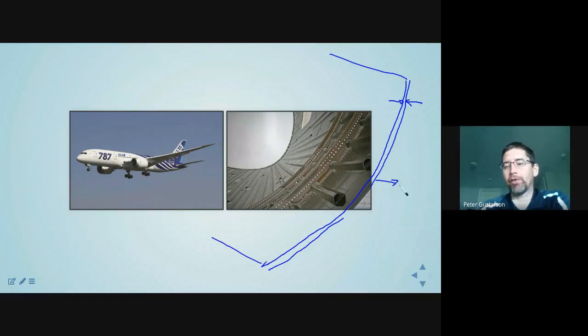Now, there's atmospheric pressure perhaps on the outside, and there's something perhaps slightly different than atmospheric pressure on the inside. These aircraft are often pressurized. So there might be an internal pressure and an external pressure, both of which are relatively small. If we're thinking orders of magnitude, you can think of atmospheric pressure as being 10 to the 5th pascals, which is a far cry from hundreds of megapascals. So it's 100 kilopascals versus 100 megapascals. 100 megapascals is closer to what the material might fail at. So we're talking on the order of 100th to 1,000th of the in-plane load that it could potentially carry, relative to the out-of-plane load that it is carrying.